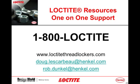When you use a red high-strength product, it can cause some difficulty disassembling, but it's often dependent on fastener size. For example, if you're using it on a 3/4 inch and up bolt, you can use a high-strength thread locker, and it comes apart with the same tool you put it together. But when you deal with fasteners smaller than a 1/2 inch, that's where the strength recommendation is more critical. The key is to use a removable grade from the start, and then there's no issue with removability.